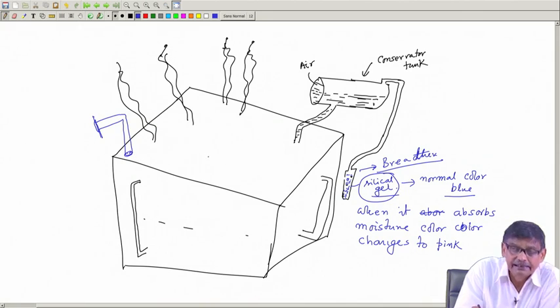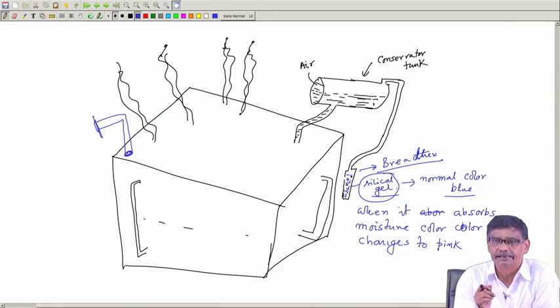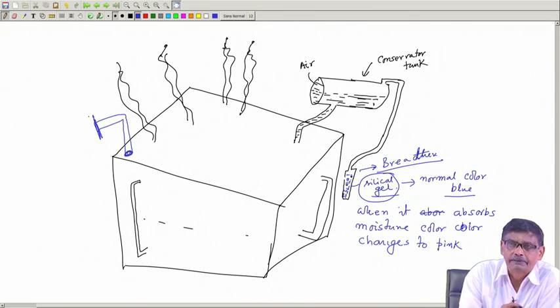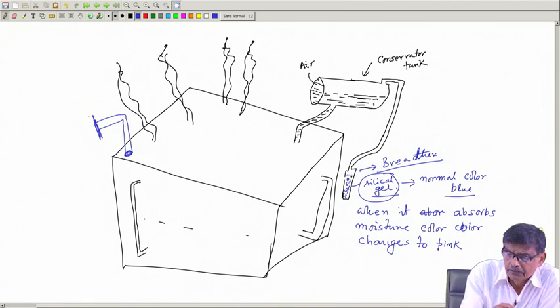But this tank, as I told you, is made of steel. Here also a not strong steel material is used, a rather little sheet of iron or steel is used while fixing it. Got the idea? The steel thickness of the tank is quite thick, but here it is only little thickness. Okay. Therefore, neither oil nor air is allowed to come in, because this end is also fixed by a plate. Therefore, no question of oil communicating with air through this.